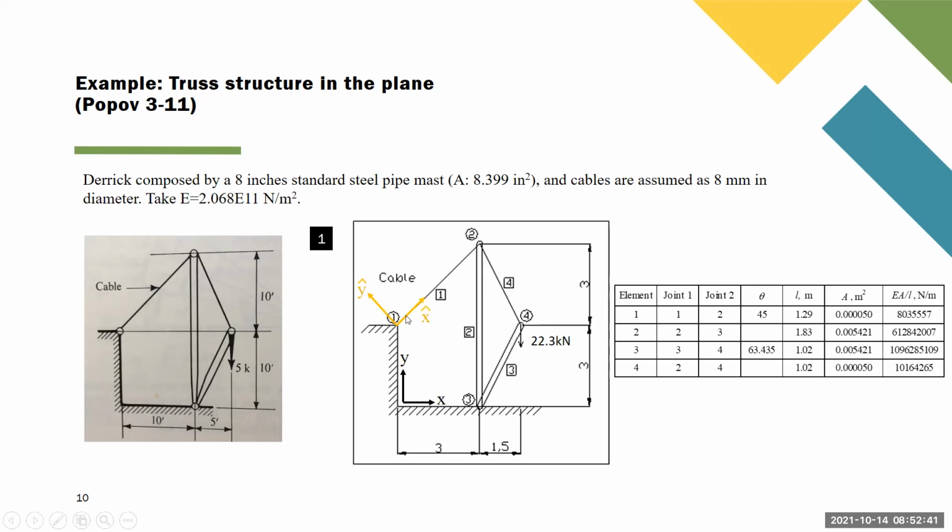So let's go. The element one. So it goes from here to there. So this is element 1. So you can see the local reference system, see? Here, I'm sorry, here I have the global reference system. So this is theta 1 for this element. So more or less it is 45 degrees. That is the value that you see here. Then you have the area, and you have these values, which are going to be common to this element.